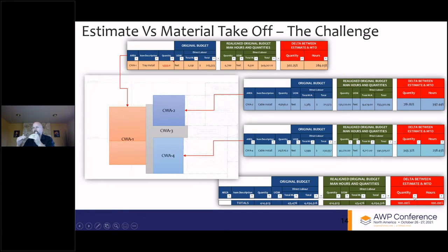What it was: the Class 1 material takeoff gets down to a tag level, and I'll jump on to the next slide. But this is definitely a challenge specifically around the E&I, and understanding that there is a definite difference between an estimate and an MTO, and that there needs to be allotted time for that transition upon or after award of contract for a contractor.